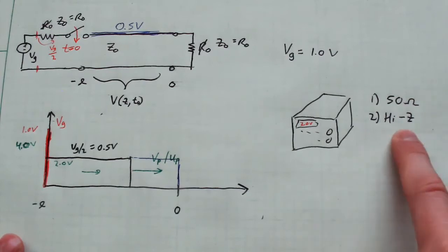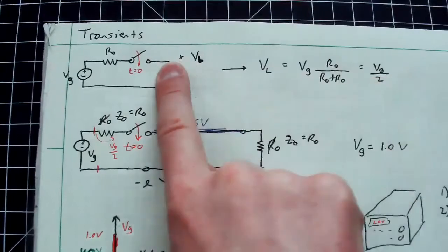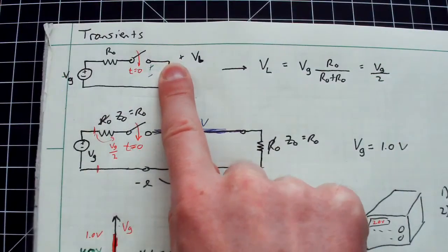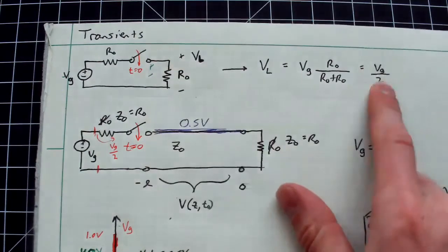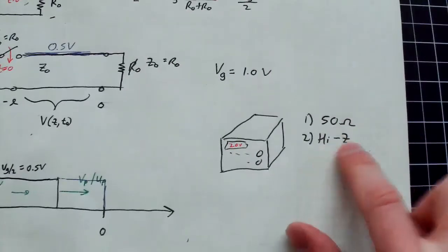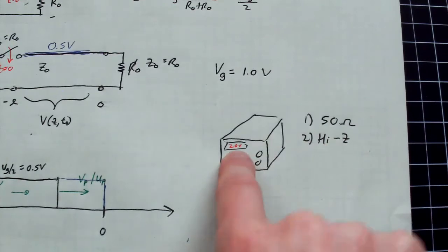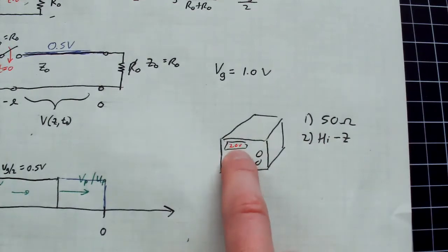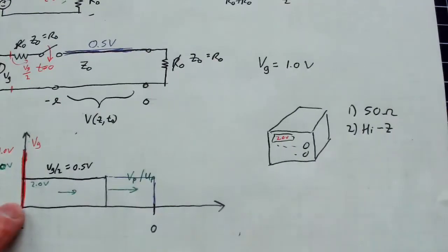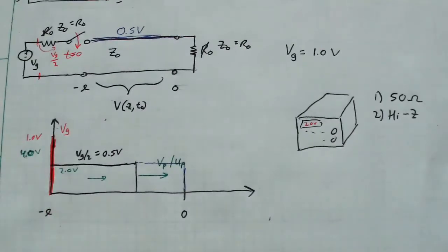So to disable that, they have this other option called high Z, which you can imagine if this resistor here were infinite, then my voltage from here to here would match my generator, because there'd be, say, no current going out. And if I put that into the divider equation, I would just get V_L equals V_G. So when you set a function generator to high Z, then the number on the display will actually be the true generator voltage. So just a sidebar of this notion that the true voltage on the line will be some voltage division relative to the actual generator's voltage.